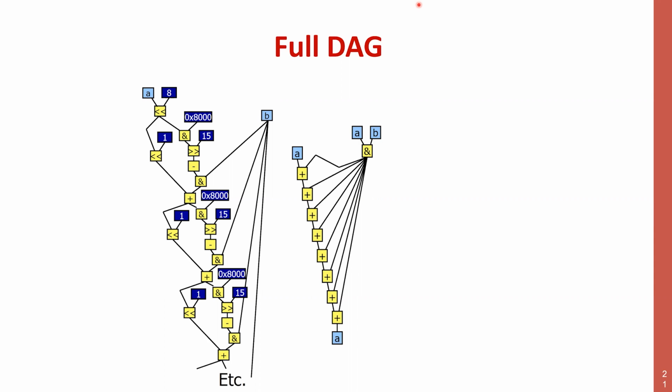So you understand that in some sense, they do exactly the same job. They remove one addendum, except that the carry save adder can be done in O(1). It doesn't depend on the number of bits, whereas any other adder is O of something, typically maybe log n in the best cases, where n is the number of bits.